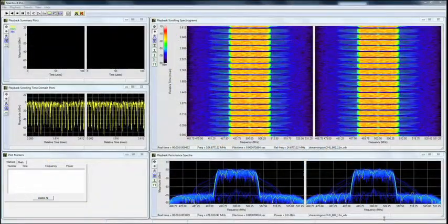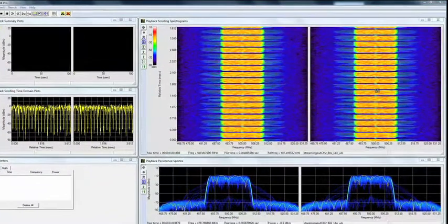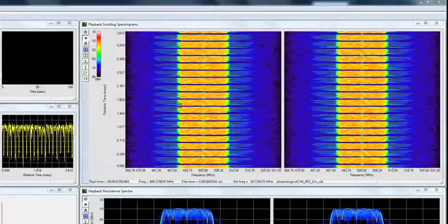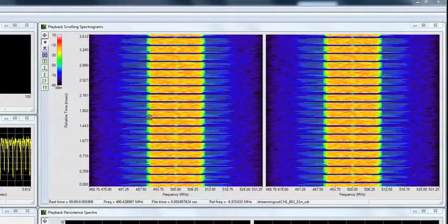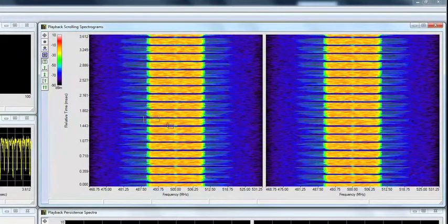To illustrate these, let's look at a recording of an 802.11 wireless LAN transmission in order to view details of its training sequence, which is a carrier-suppressed phase-modulated portion of the 802.11 frame. Here we've got two channels of 802.11 data. For this demonstration, we'll just deal with channel 1 on the left-hand side. And first we'll zoom in down to an individual frame.